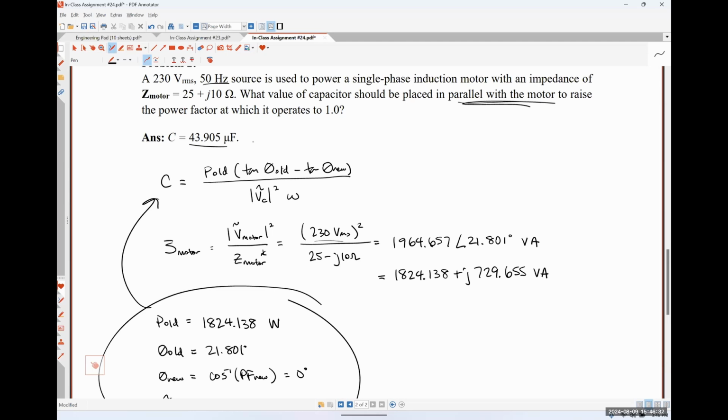So whenever we're trying to do what's called voltage regulation on the utility grid, which is making sure that the voltage never dips below a certain threshold, which could cause damage to electrical machinery and stuff like that, we actually have to make sure that we place capacitor banks near those systems so that the voltage never drops down too low and shuts things down.